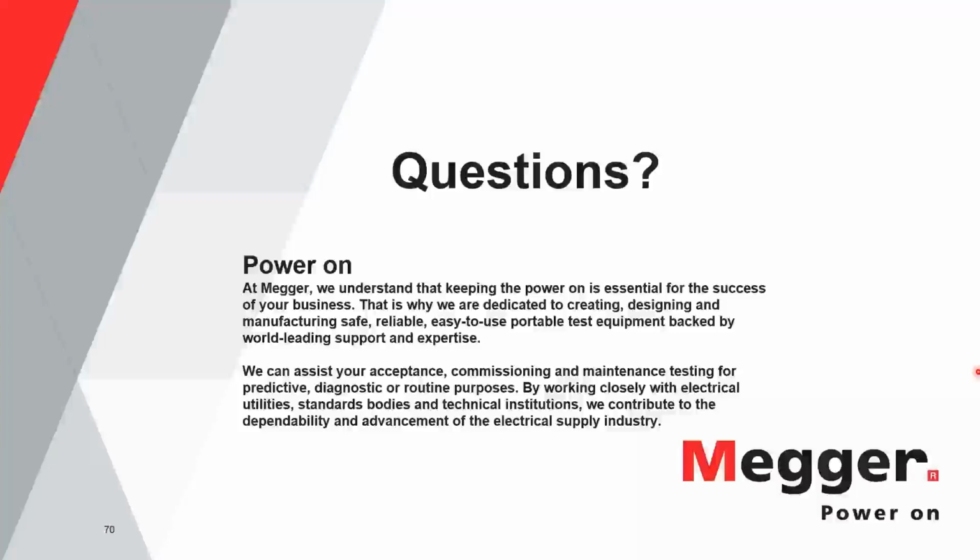But once you're at that point, if you're at, say, a 121 kV or 245 kV transformer where you can get to the bushings from just standing on top of the transformer, you could really do this test, all 15 of them, on a 2-winding transformer in I'd say 45 minutes to an hour. But that's, of course, the transformer's already isolated and everything like that.